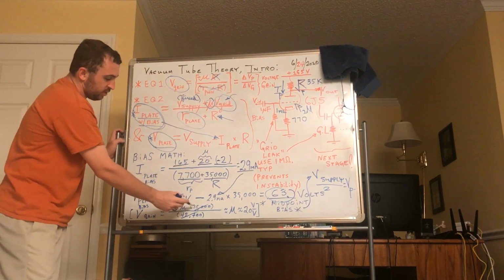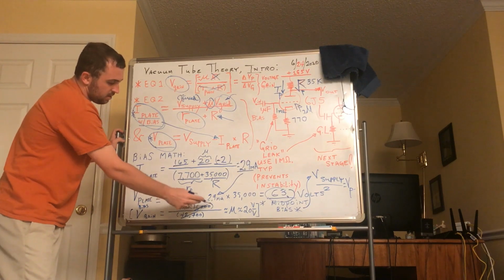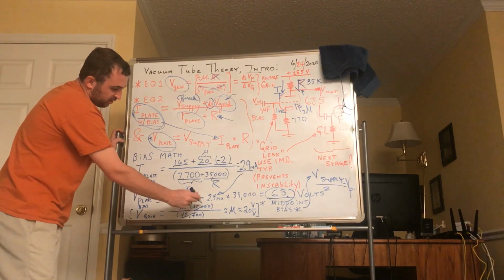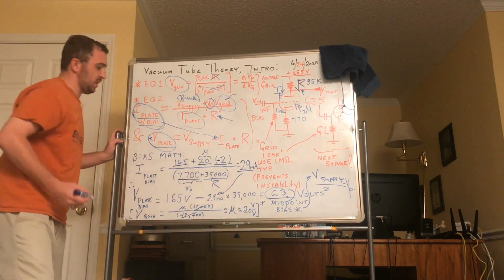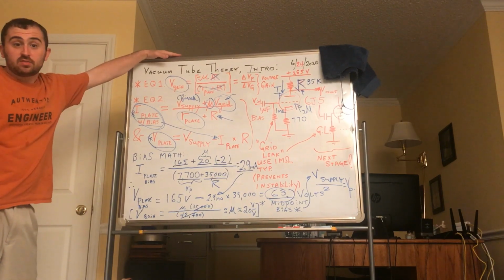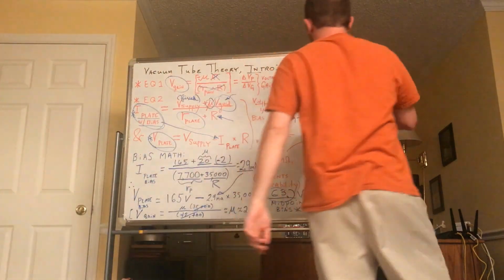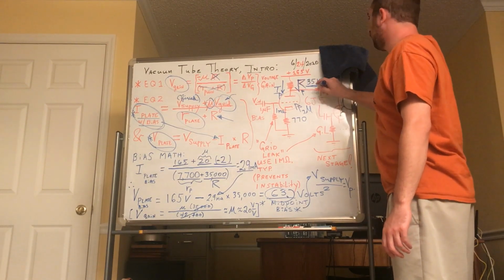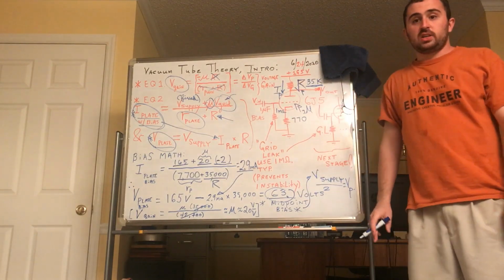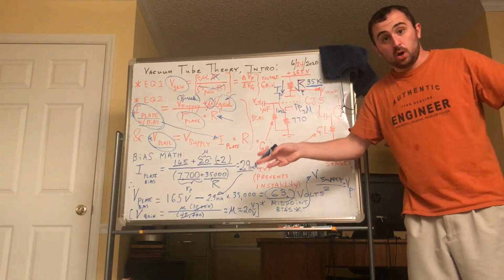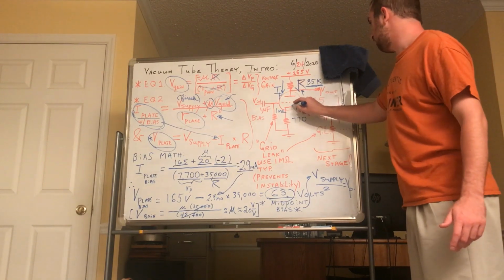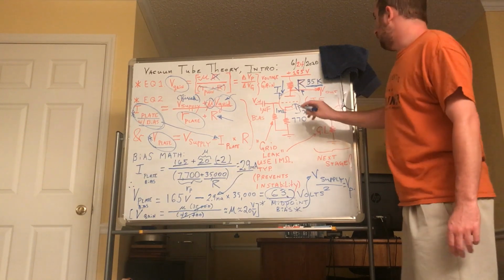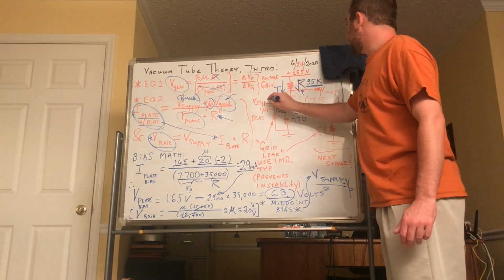Then we work the math, and as you can tell, big R, 35K, is dominant. It's 35 over 42K. You can roughly cancel that out, and the voltage gain is roughly mu, or 20. All of this was derived in the previous video, and so now we have our circuit. We chose 35K based on bias and gain concerns. And you can fiddle with these formulas and choose values that give the right bias or the right gain or both. Or you can change the tube if you need a different parameter of R plate and mu. And then we biased the grid with a minus 2.